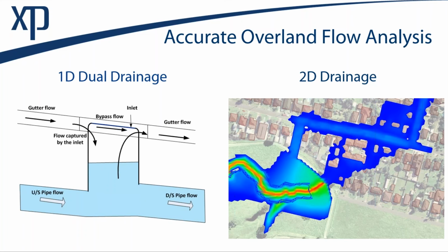Whereas the graphic on the right is representative of what happens with 2D drainage. So the 1D model is linked to the 2D model. In this case, our 1D model is this channel over on the left, and we can see this pasture land here, and the channel is overflowing into the pasture land and up against probably this berm area that's beside the road. It finally overbanks the road, and then it impacts our little town or our village here.